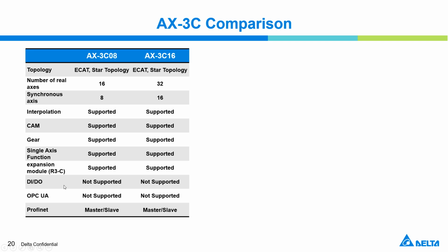And here you need to know that for this module, because it's the slim model, it does not support the built-in DIDO. And the OPC UA function, this module actually doesn't support it, and for the Profinet, it supports master and slave.